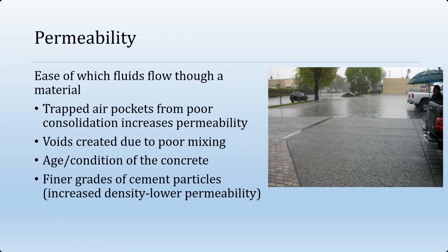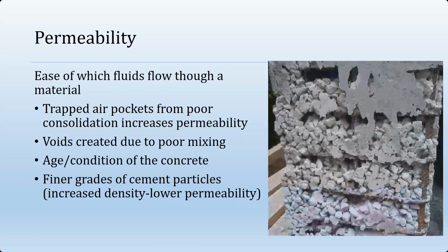Permeability is defined as the ease with which fluids flow through a material. Trapped air pockets from poor consolidation, i.e. vibrating of concrete, increases that permeability. Voids created due to poor mixing, the age of concrete, finer grades of cement particles, all lead to higher permeability. And concrete obviously never remains ideal over its service life, and likely may increase this permeability over time. Certainly, this never happens, and we never see this on projects.